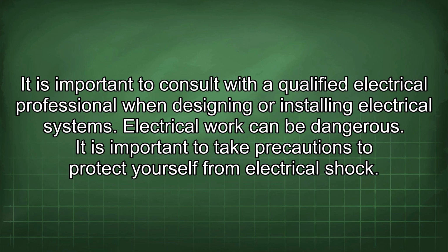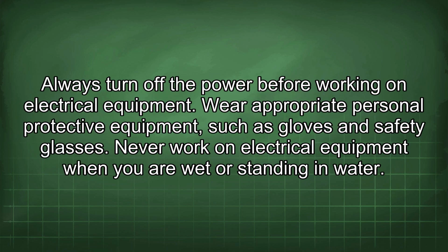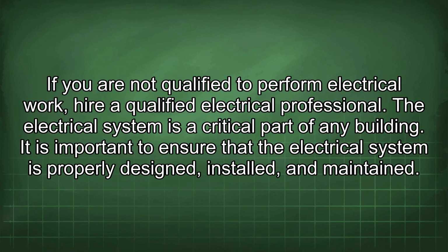Electrical work can be dangerous. It is important to take precautions to protect yourself from electrical shock. Always turn off the power before working on electrical equipment. Wear appropriate personal protective equipment, such as gloves and safety glasses. Never work on electrical equipment when you are wet or standing in water. If you are not qualified to perform electrical work, hire a qualified electrical professional.